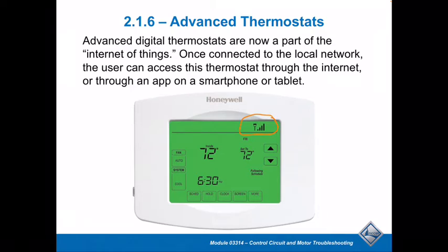Many of the Wi-Fi thermostats, however, do require a common connection. Now, they don't all do that, but many of them require, on the wiring side of things, all of your normal wires, but now you're going to need a common to actually operate the thermostat. That's a typical way to do that.